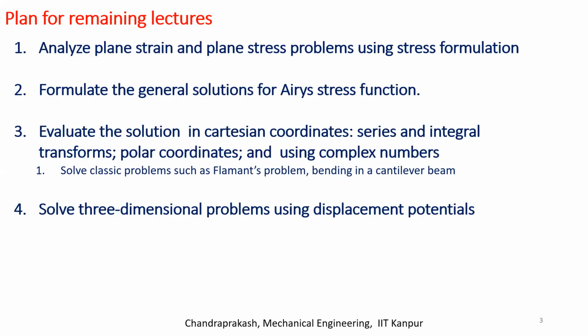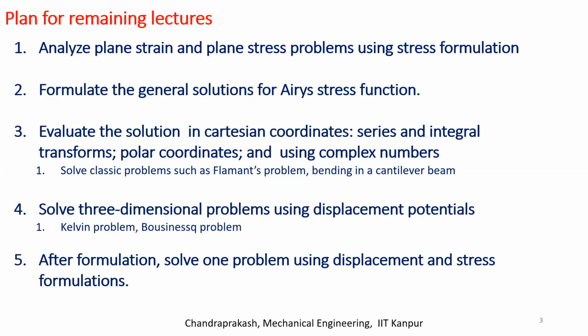And we will solve some problems using displacement potentials as well. We will analyze plane stress problems and plane strain problems, and in both these kinds we will solve using stress formulation as well as strain formulation. So you will solve problems which cover this entire spectrum. In displacement potentials also there are some classical problems such as the Kelvin problem, which is nothing but an infinite object with a point load acting on it. And we will also solve at least one problem using displacement formulation and stress formulation,